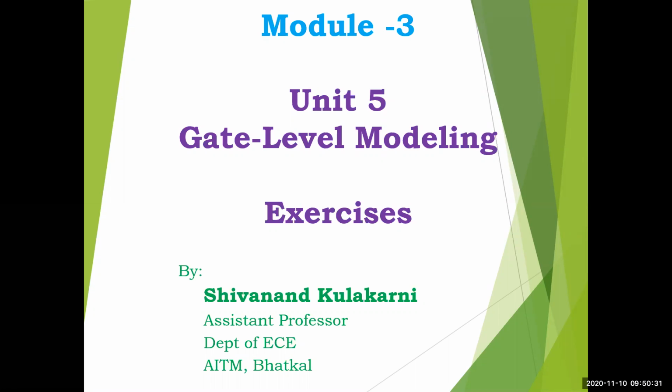In the previous video, we discussed two exercises. One is about designing your own NOT, AND and OR gates using only NAND gates. And from that, you designed a second exercise that is about the XOR gate. Also, you have understood how to apply the stimulus for 4 inputs, and you have seen the output.